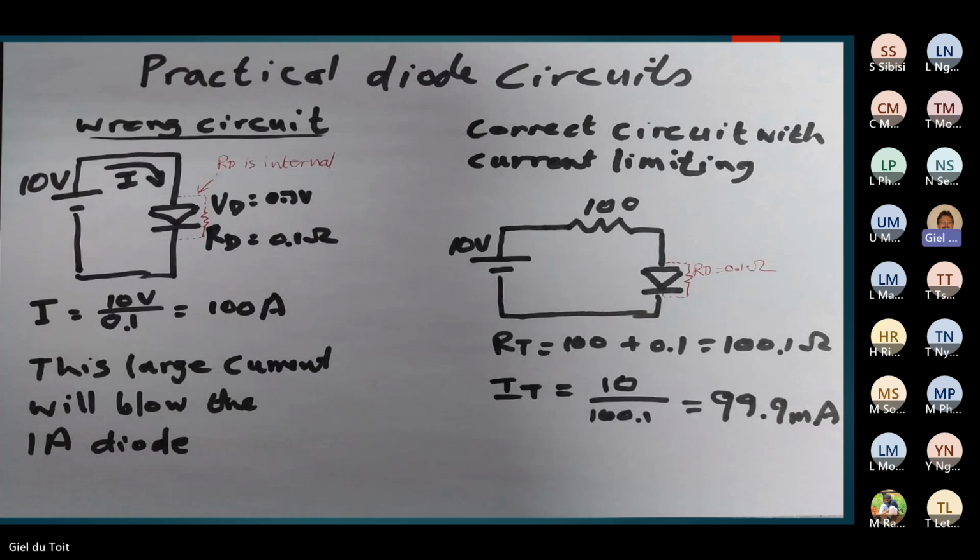In your experiments, Ian, you've seen that when you put a diode directly across a power supply like that, you can blow the power supply. You will also blow the LED, because the current taken by the LED is just too much for the power supply to supply, and you can damage the power supply too. So the current limiting resistor in this case will limit that current.